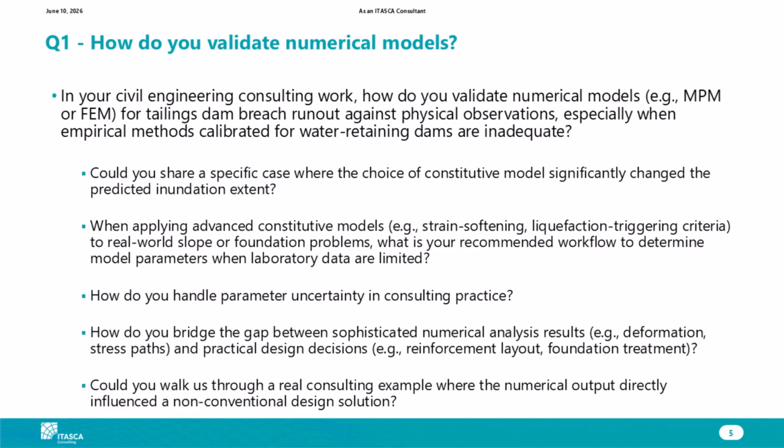Okay, I never use laboratory data, so whether there is a lot or it is limited, it doesn't really matter. The main reason is that there are very few soils that provide reliable data from lab measurements. You take the London clay, the Boston blue clay, the Bay mud, the Vatican clay, or some other region, and there is a common theme between these different units: clay. It is relatively easy to sample, so the lab activity provides a decent measurement of the parameters that we need. But in general, the vast majority of the lab activity that I've seen is not good enough to be used for calibration or to determine, let's say, numerical modeling parameters.